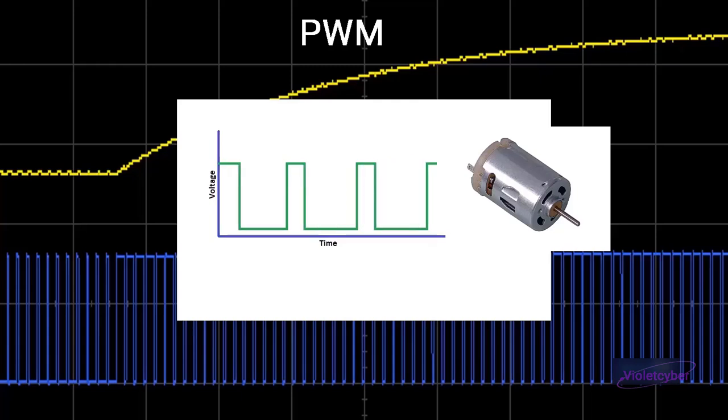But it is not a standard method, and in addition, from now on we will be dealing with digital circuits and microcontrollers. Digital circuits that are programmed work with PWM pulses, and in this way they can control the voltage applied to the consumer, and transistors too, based on PWM pulses, work much better. That's why we need to control the speed of the motors using the PWM method. For example, you can't define a state for the IC to boost the voltage, so how should you do this? The IC method is PWM, and with the PWM method it controls the motor and can control the voltage.